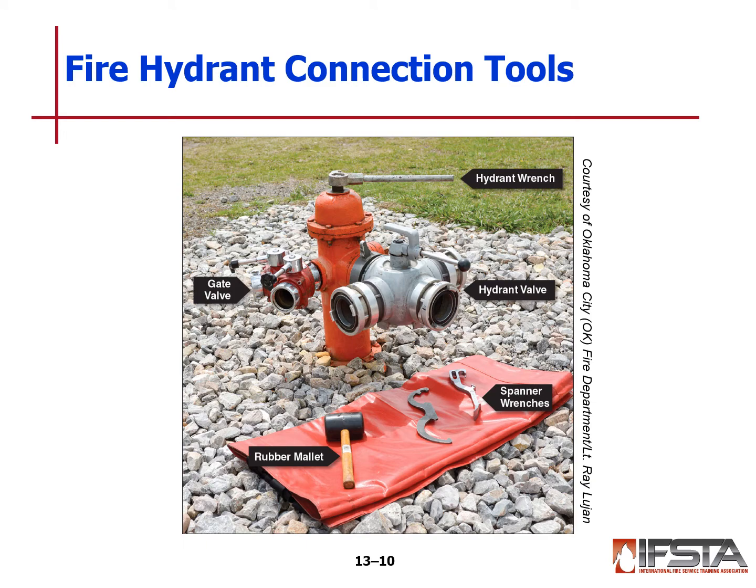Connection tools. How do we connect to our hydrant? You can connect straight up to a hydrant on the steamer side and or the hose side. Typically we will use what's called a hydrant valve or a Hydrassist valve, as you see pictured here, which is the big valve right here on the slide. That valve is designed to go straight to the pumper, and you can also boost pressure if you need to coming out of that back through the pumper. That's why it has three. It has an inlet and an outlet on the side, and then just an outlet that goes straight.